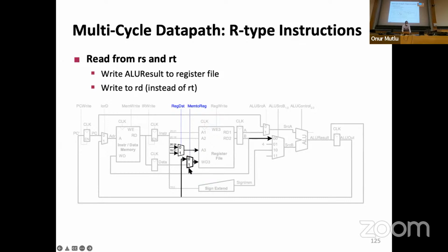And you have this mem to reg register still, because R-type instructions take the ALU result, latched ALU result, and write it into the register, whereas the load word takes the latched memory output and writes it into the destination register. So we need to add this mux to support both the latched memory output as well as the latched ALU result to be written into the register file. Right? And that's the idea, basically. And this is the other thing over here.